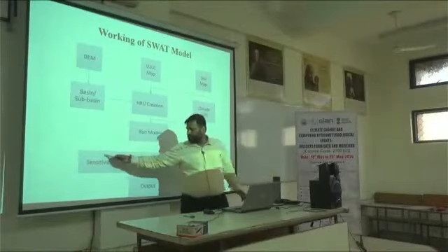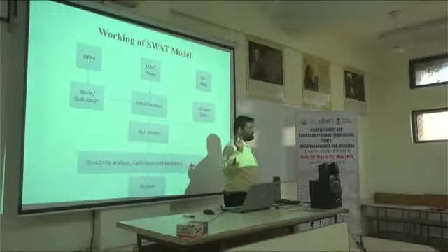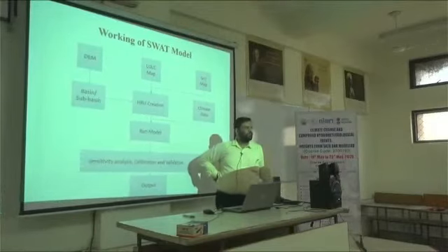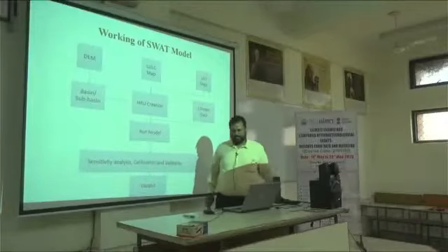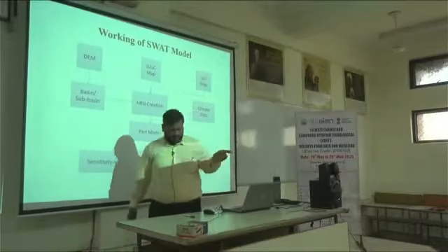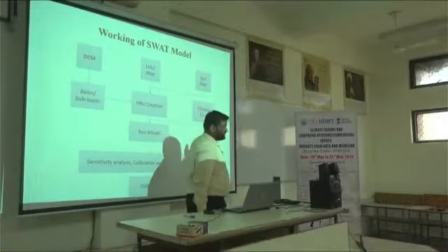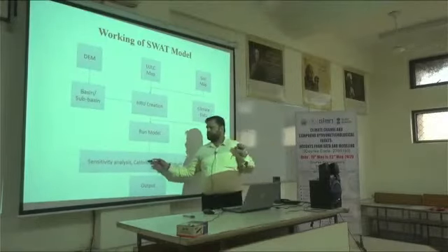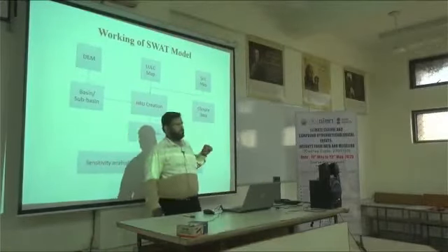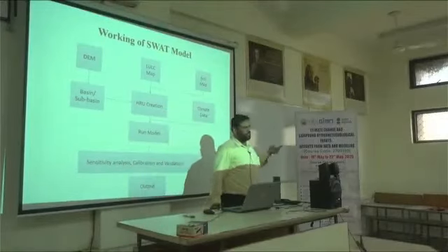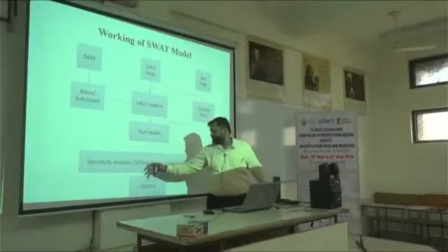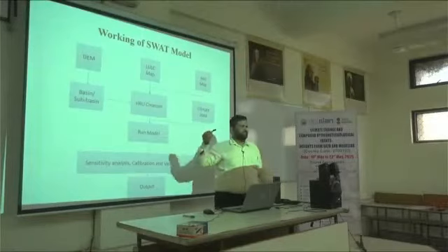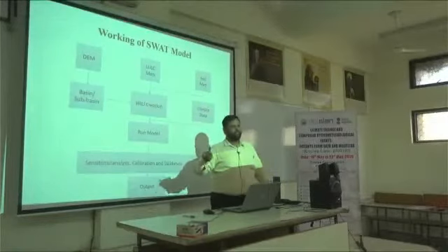For that, there is also sensitivity analysis. As I have already mentioned, for discharge calibration we have around 50 parameters. All 50 parameters might not be useful for our calibration purpose, so we have to reduce them, and we can do some kind of sensitivity analysis. There are different methods for sensitivity analysis, calibration and validation. There is stand-alone software known as SWAT CUP, the calibration and uncertainty program.